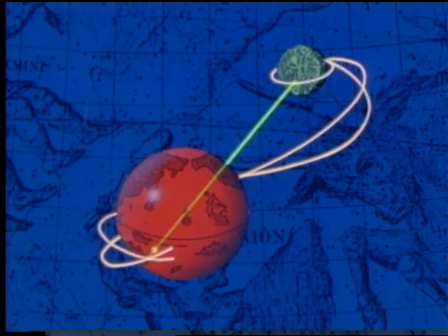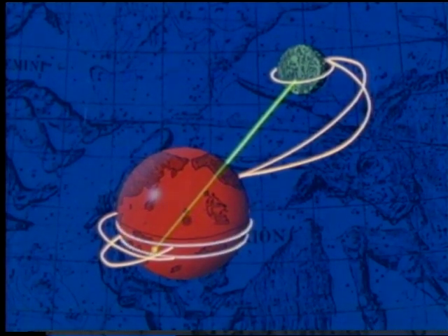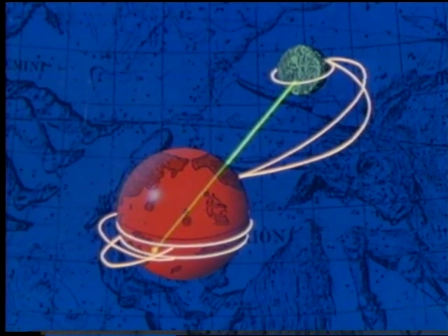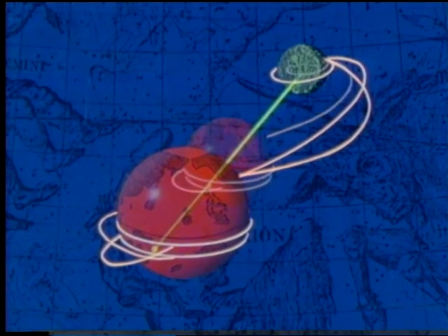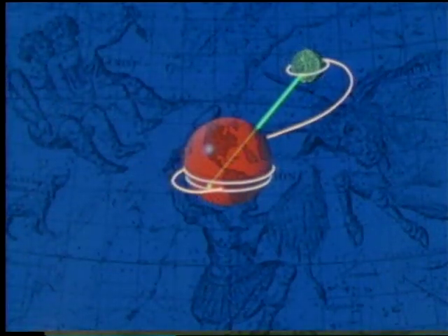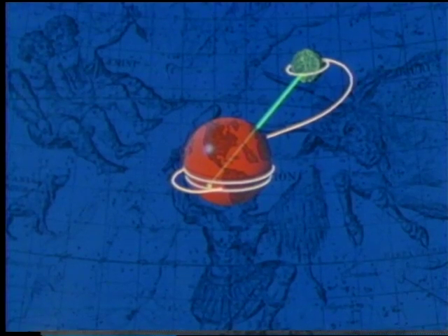This range of planes, along with the entry range limits, determines the range of latitudes that can be achieved. Because of the relatively short entry range, and thus the small distance from the antipode to the target point, it can be seen that the latitude range is quite small. The landing latitude selected within this range is essentially fixed at time of trans-Earth injection.